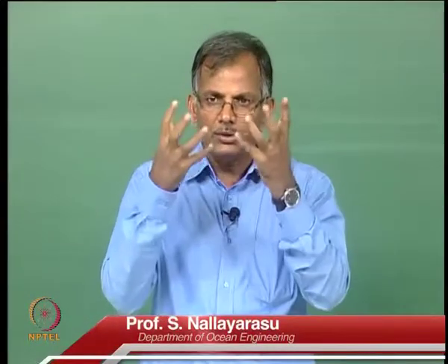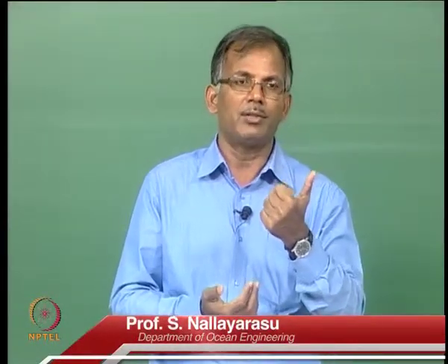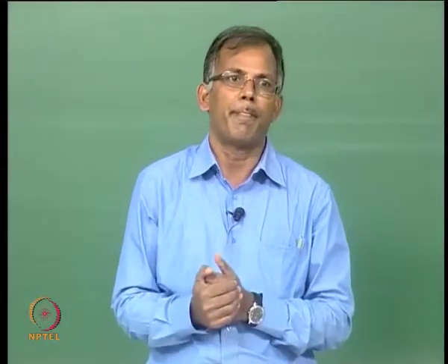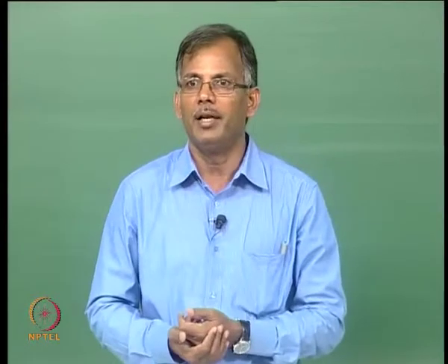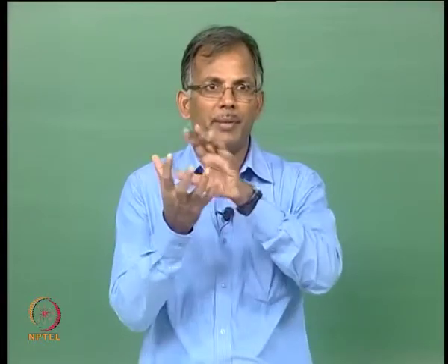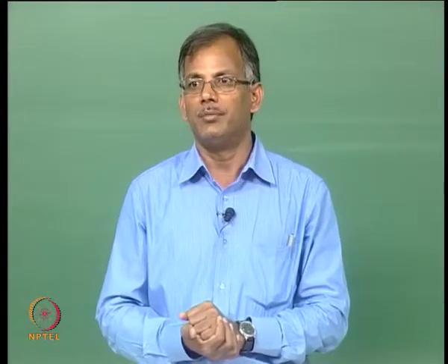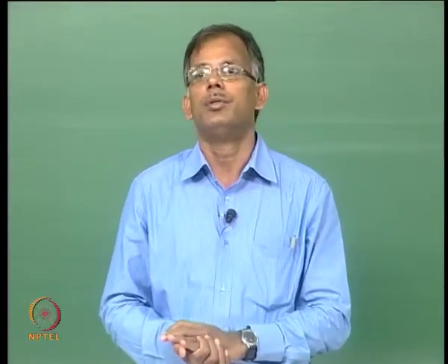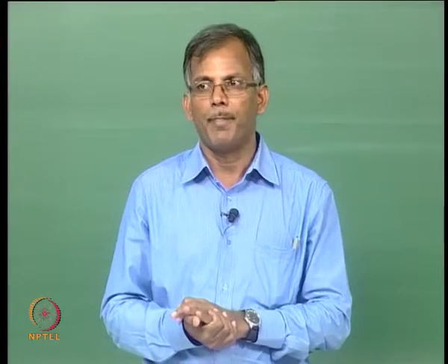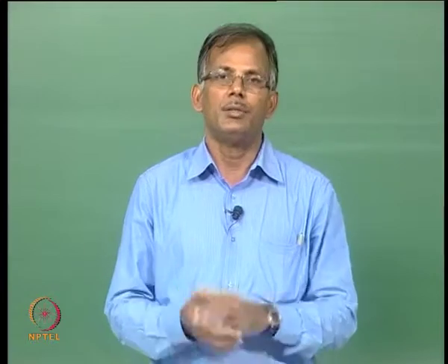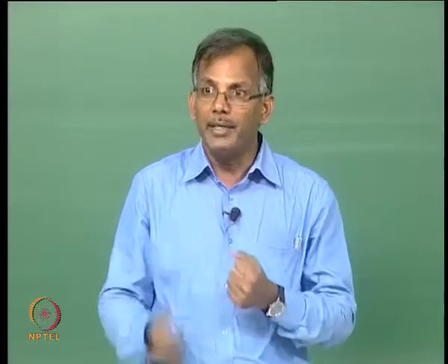So, you can see here soil is definitely going to absorb, depending on what type of soil, whether it is a rock. For example, you take a nail and strike it against a hard rock, what will happen? The rock will not absorb any energy. To absorb energy, what do you require? You require settlement. You need to have the material get compressed. If you have a very hard rock, what will happen? The pile will jump upwards, because there is no absorption there. If it is a soft material and the material gets compressed, then the energy is absorbed, and the remaining energy will reflect back.